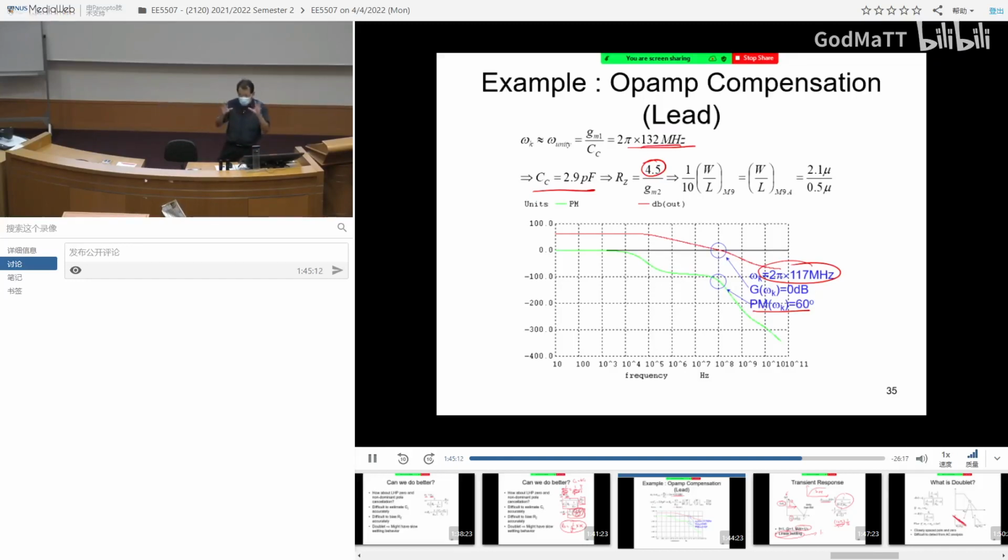So it's like there are two big guys in this room. My whole attention only focuses on these two guys. All the rest, too small. I don't care. But once I remove these two guys, the others become significant. You get the point? Okay? So that is the reason why you can never get 90-degree phase margin. When you remove this, something pops out. But that is good because that something that pops out is so far away. So that allows you to widen the bandwidth further.